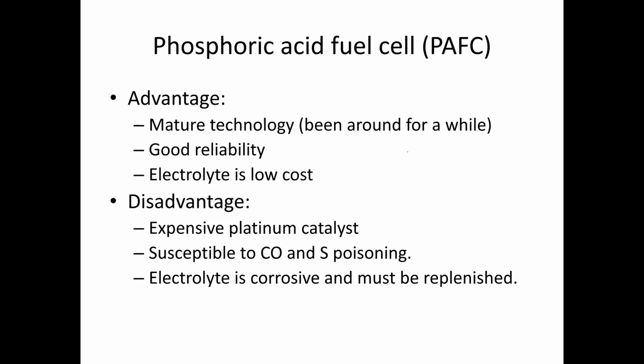One advantage is that it's been around for a while, so it's mature technology. It's reliable, and the electrolyte does not cost a lot of money. But the disadvantage is that the electrolytes a lot of times are platinum. I'm sorry, not the electrolytes. The catalyst is platinum, very expensive, and the fuel cell itself is susceptible to carbon monoxide and sulfur poisoning, and the electrolyte is also corrosive, and it must be replenished.